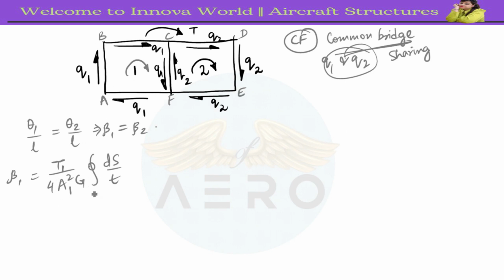If the material is the same, then G1 is equal to G2. If not, we can consider that also. Let's assume that the materials are the same for simplification. And here A1 is also equal to A2 equals A. We can consider that, but we cannot consider that T1 is equal to T2. These are the conditions. So let's assume theta 1 equals T1 by 4A squared G, closed integral ds by t.